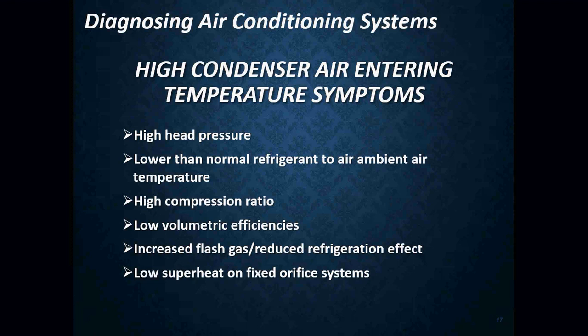Your high outdoor ambient temperatures will cause high head pressures to elevate. Okay? The temperature difference between your condenser temperature and ambient temperature will go down, and the refrigerant gas will not condense until the head pressure actually rises.